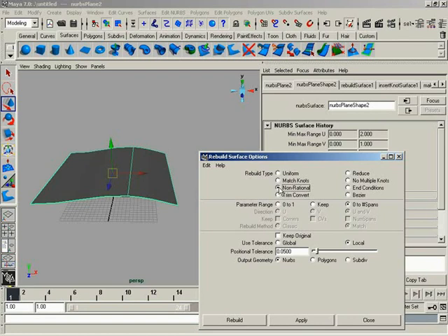Because of that, the ability to change the weights of NURBS CVs has been cleverly taken away from you. And the reason for that is because a surface that has even spacing, even weighting on each CV, a non-rational surface in this case, is much easier to calculate. It's a lot faster. So to keep things nice and quick, and because you'll probably never need the power in the first place, you do not have the ability to adjust the weights.